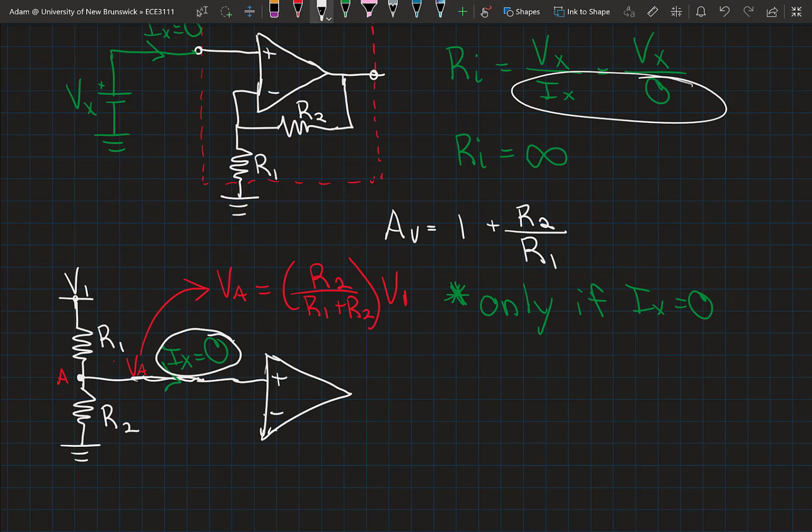But you might say, maybe I don't want to put a gain on this signal. Maybe I want this voltage VA. Well, here's a very special and useful configuration of an op-amp: connecting the output directly back to the input. We know that because the op-amp has a gain that's very high, or assumed to be infinite, whatever voltage is at the one terminal also appears at the other terminal. So the voltage at this terminal is going to be the same as the voltage at this terminal, which was VA. And this voltage here is tied directly to the output, so the output is also going to be VA.